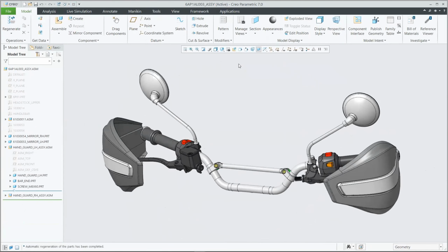So that's really what ISDX is all about at a high level: being able to start with whatever it is you have, whether that be some simple reference geometry, maybe some images. Even if you don't have anything, you can just set up some planes and start creating curves between those planes. Utilize that 4 view to really get an idea of how those curves look in 3D space without having to continually rotate around any of those curves and adjust views. Gives you a nice look at all of that at the same time.